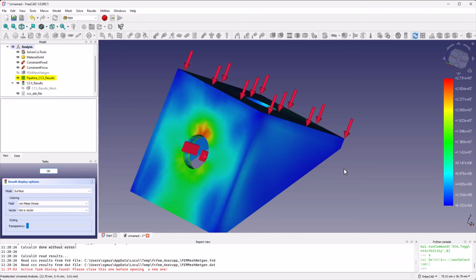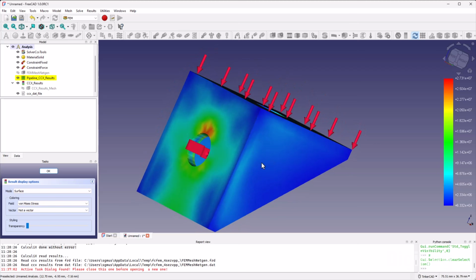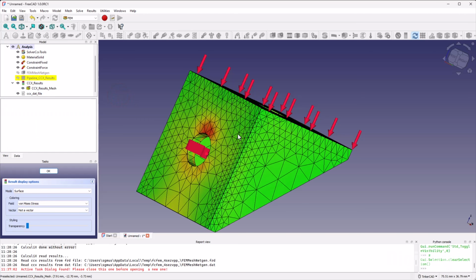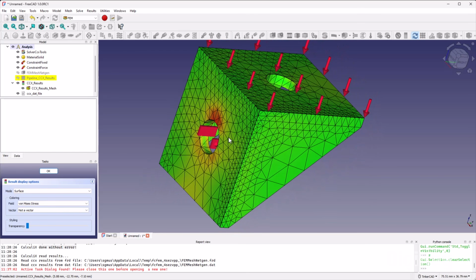The British statistician George E.P. Box is often attributed for the quote, "All models are wrong, but some are useful." This applies to finite element analysis as well as statistical models. In other words, take all of this with a grain of salt and try to take a holistic view of your design. Due to the discretizing of the part into mesh components and numerical estimations, the stress numbers won't be exact. Stress patterns and how much general deflection happens are often more useful than figuring out precise numerical values.